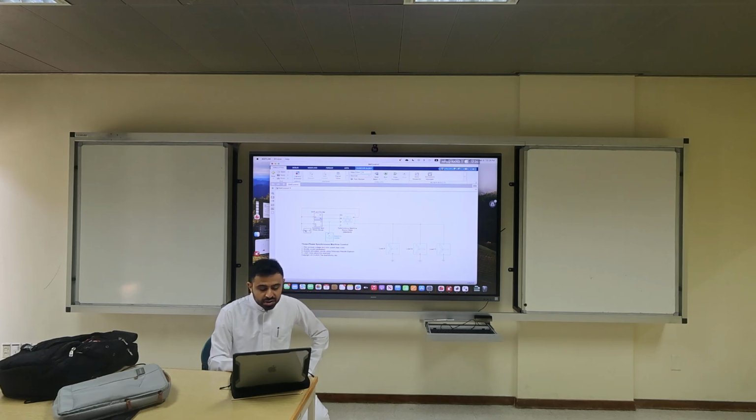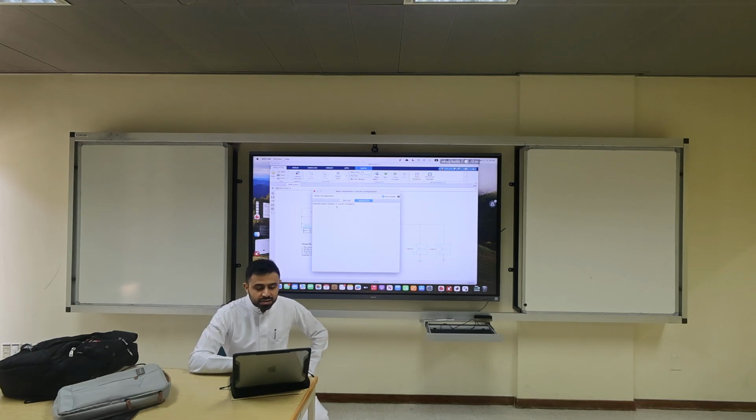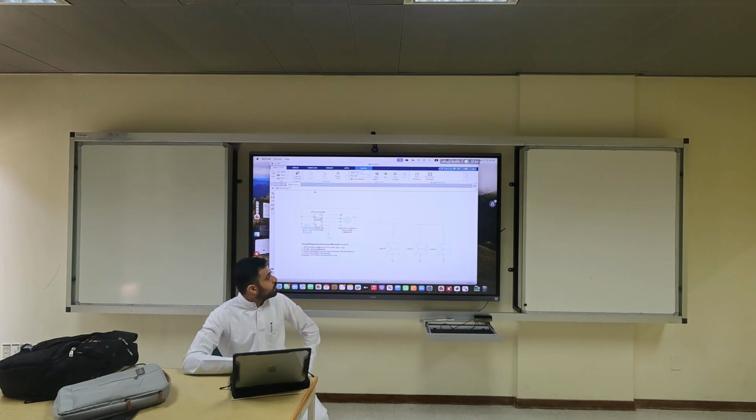So done with this. What is this function? Solver configuration. This is usually in MATLAB, it solves first order, second order equations. Leave it. It's here for a reason. Usually it's put to initialize the vectors or the data. At the beginning we have these transients, so it solves them. And this is just solver settings for the simulation. Don't change these parameters. There are engineers who work with Simulink who already made it for you.